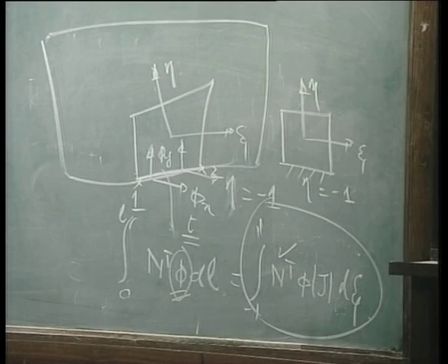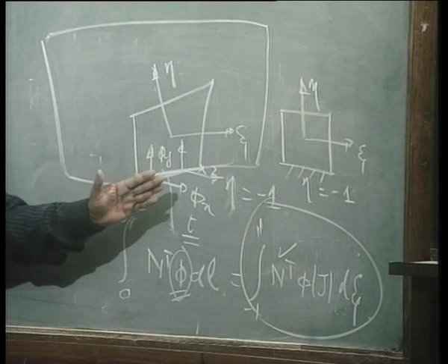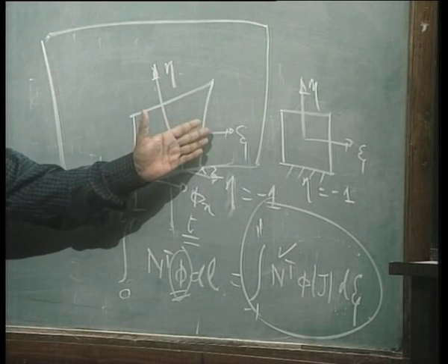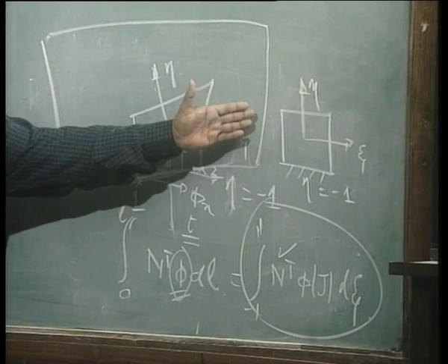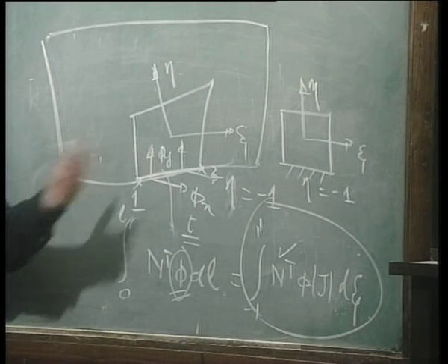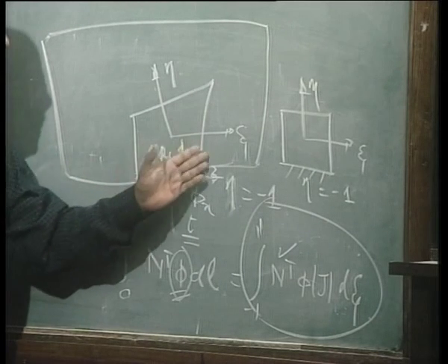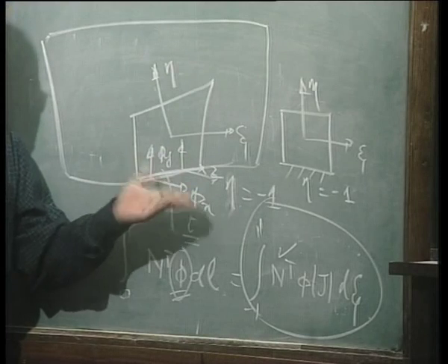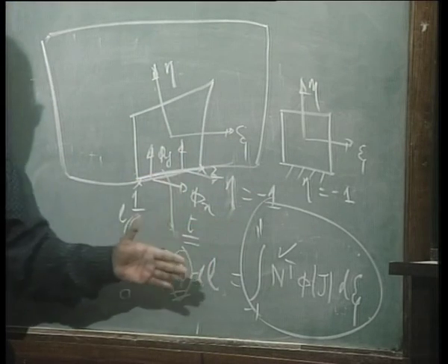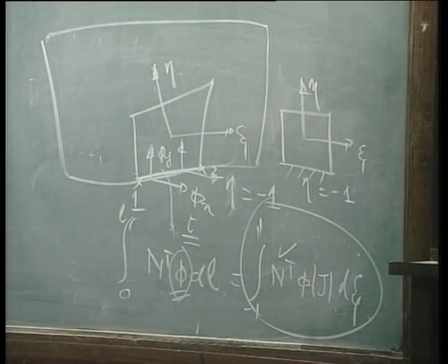So that is a very important thing. And the other one is that this is only an example for eta equal to -1. It so happens that the same element may be at the other end, at the other side of the boundary, and so we may have to apply pressure not at eta equal to -1, but say at psi equal to 1 and so on. So you have to be properly accounting for the surface where we give this pressure.